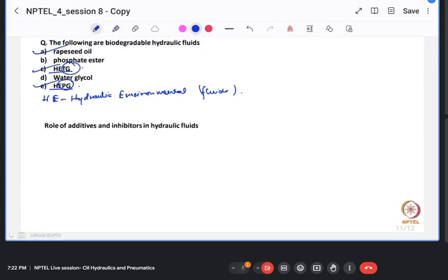While you are selecting any particular hydraulic fluid, hydraulic fluids can be of different types. It can be water-based fluids or oil-based fluids. It can be some synthetic hydraulic fluids, or some biodegradable hydraulic fluids. Not all the fluids are applicable under all conditions of pressure, temperature, and other environmental factors, so they need to be chosen very judiciously before being used.